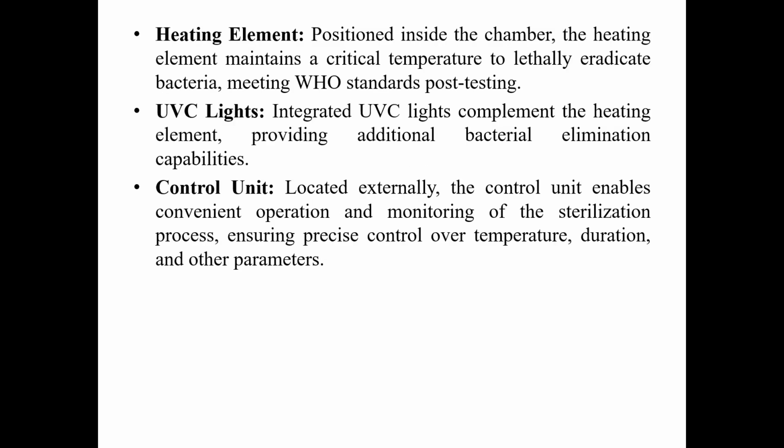Now we are going to see about the heating elements. The heating element is positioned inside the chamber. The heating element maintains a critical temperature to lethally eradicate the bacteria, that is 60 degrees Celsius or more than 60 degrees Celsius, within a time duration of 10 to 30 minutes, meeting WHO standards post testing. I've already mentioned that I have attached a UVC light to produce UV. It is integrated with UVC lights, complementing the heating element, providing additional bacterial elimination capabilities.